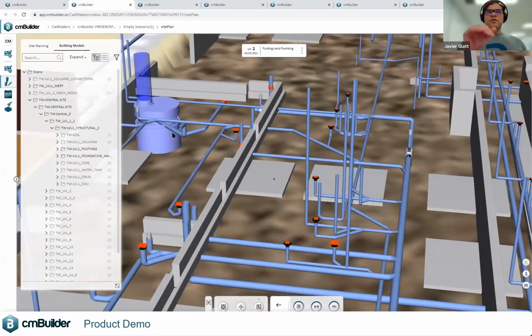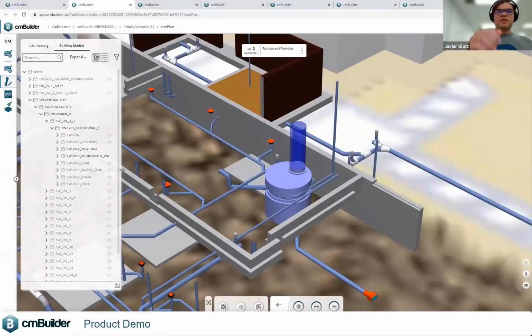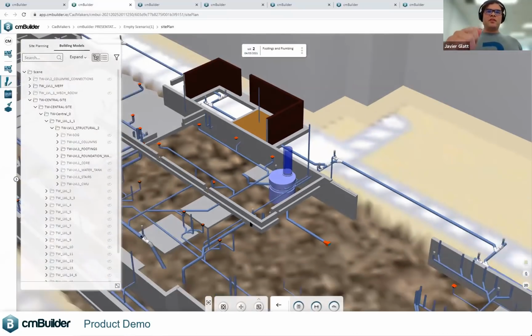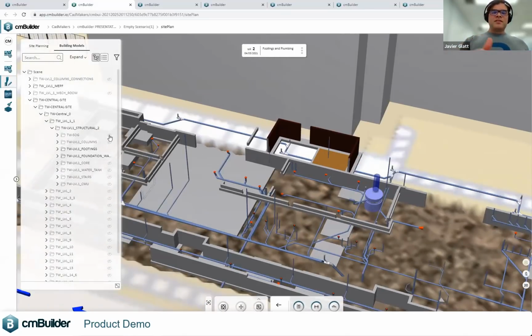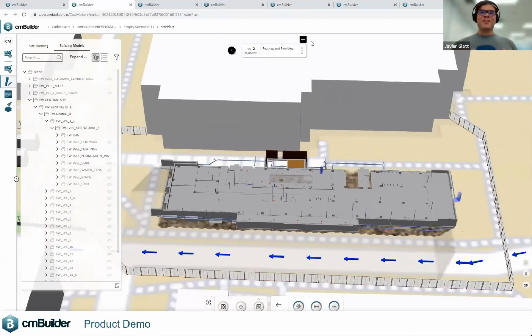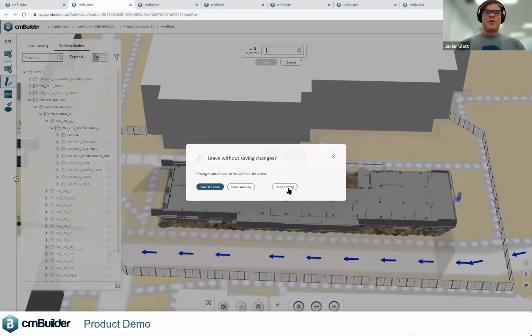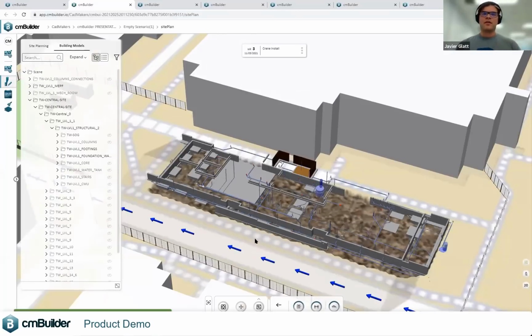Now, one thing that's nice here, we've brought in the model. In this case, there's a BIM model created. You don't always have that, but you can start planning your sumps, footing elevations, slab on grade, this type of stuff. Now we'll get to the next topic here, which is placing the crane. It's a big discussion. Just about every job, placing the crane is something that keeps people up at night. So now that we have the footings and foundation visualized on the site, let's go ahead and show you 2 ways to model your crane on a construction site.